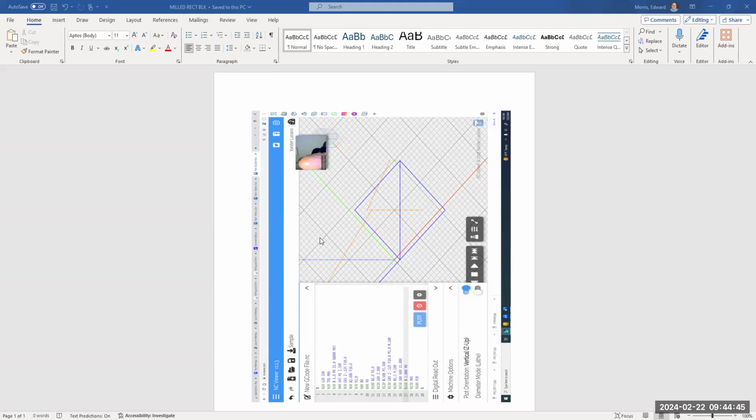Like, for example, you'll say G20, and that means you are programming in English units. And G90 means absolute position, okay, with respect to 0, or your origin. Then you might say, what is T01? That's tool 1. And M06 means you do a tool change, you turn the spindle on, and then you go to your first position and so on. But we'll do that on Tuesday.